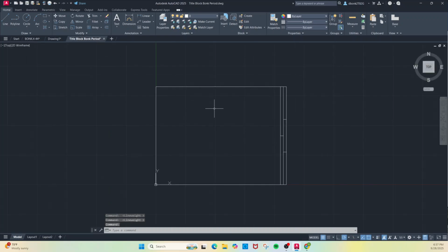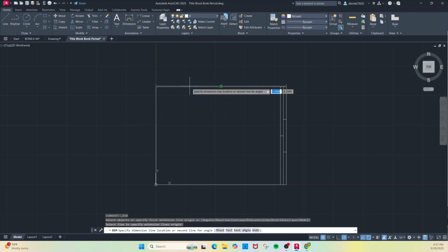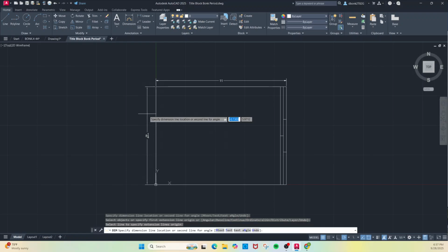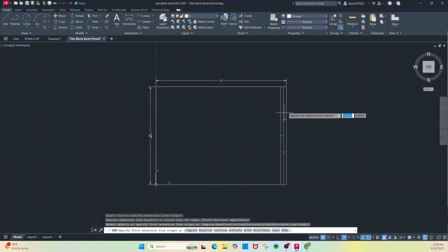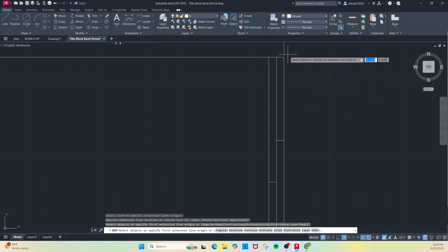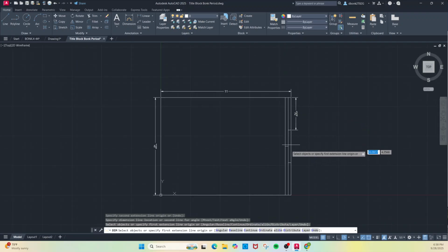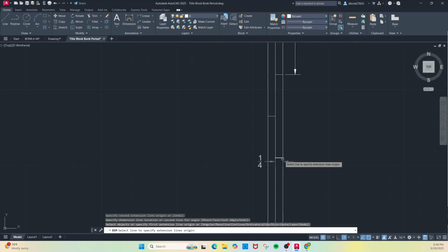So anyway, those are weighted now. We selected them. We weighted them to 1 millimeter. We have our line weight button on here. We can put some measurements on here now. We can add our dimensions by clicking line once, moving away about a grid block. And then chaining measurements like these on the right side here are done by clicking to endpoints and snapping them together.